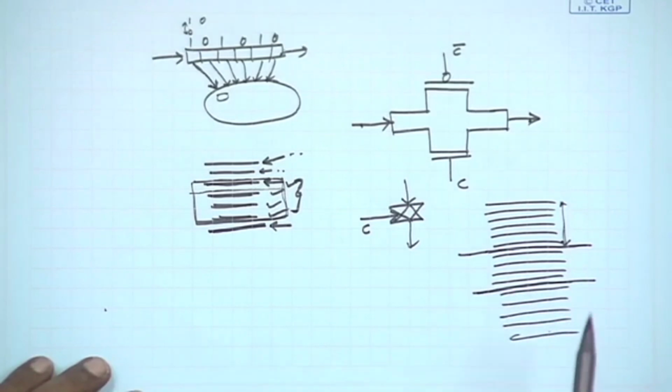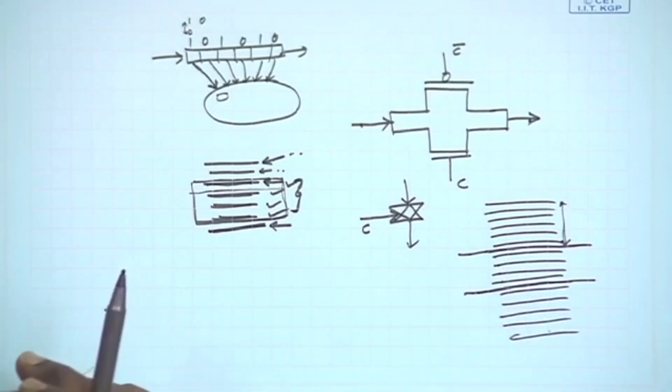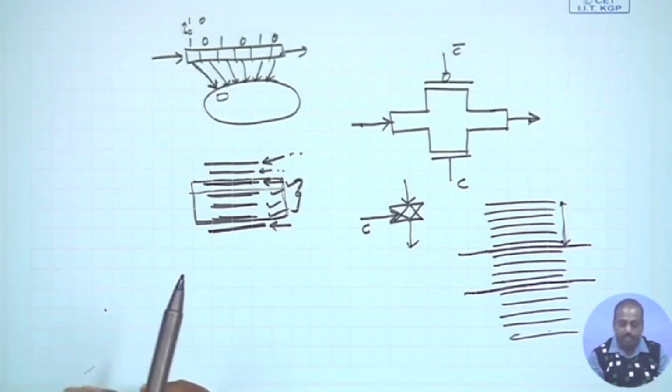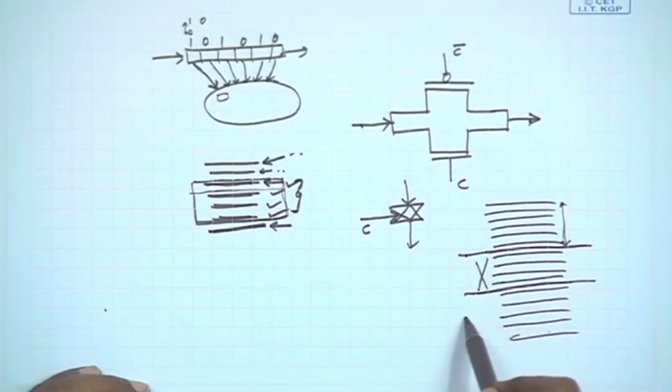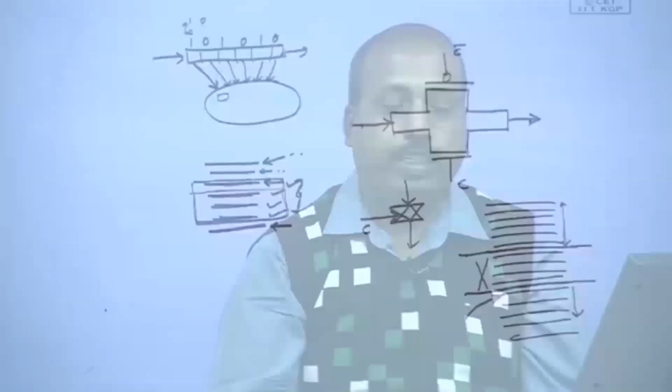So, in the previous case, in the BIST filtering case, these filtered patterns were not allowed to appear at the circuit input, but the LFSR was generating these patterns. Now, in this reseeding approach, we do not generate these patterns as well; rather, after this the LFSR is reseeded with this particular value. This value will be loaded into the LFSR, so that it starts generating patterns from this point onward. So whenever we find that this LFSR is not generating any useful pattern, we change the seed value of the LFSR, so that it generates patterns in the region where it can detect the faults.